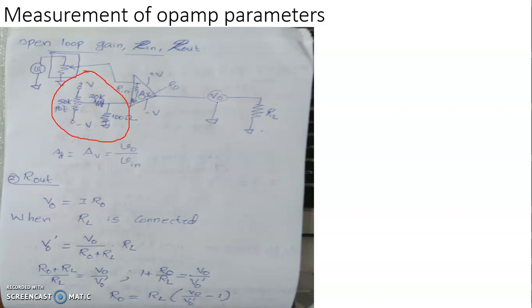If there occurs an output voltage, then that will be the amplified portion of the input offset voltage. This must be supplied in a negative manner in the input or as a differential voltage in the input, so that the output voltage becomes 0. That is in fact the definition for the input offset voltage. This is the voltage that must be applied between the two input terminals as a differential voltage, so as to reduce the output voltage to 0 when no signal is applied to the opamp.